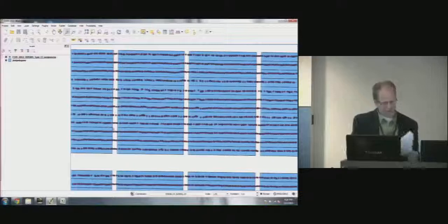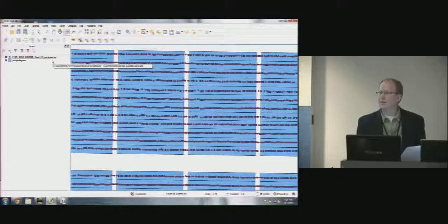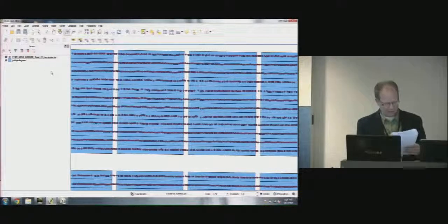Okay, so one technical detail then is that when we loaded this file, it's still a comma delimited file as it sits right now in the GIS. And so in order to be able to do any geoprocessing on that file using the native scripts within the GIS, we have to actually convert this CSV file to a shape file. Remember I mentioned the shape file on Monday is the standard format for representing geospatial data. So we can do that.